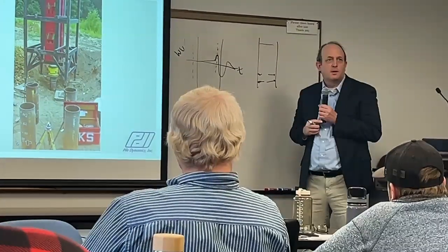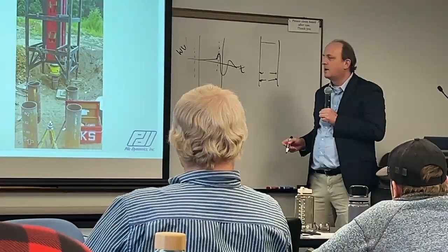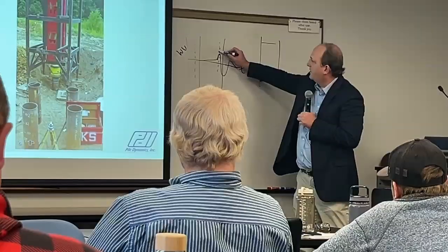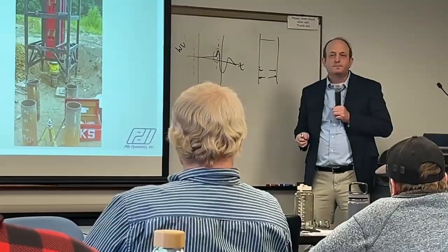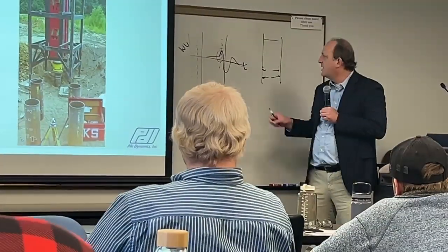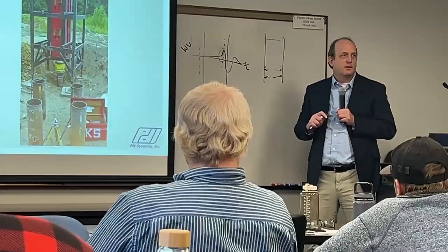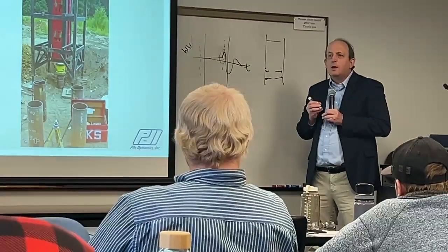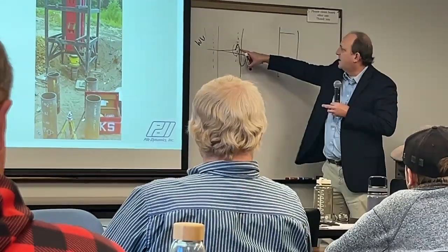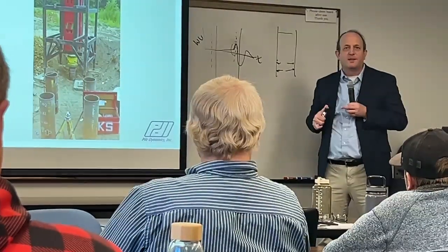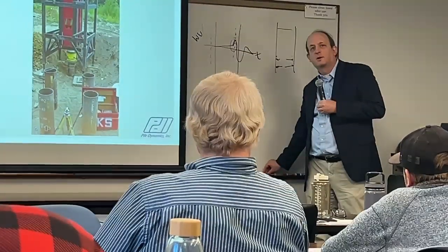When we're looking at open piles, especially 24-inch open piles, this is the behavior of the soil sitting inside the pile. So part of that will be modeled as resistance, and part of it gets modeled as additional mass, or as additional impedance, basically. As those piles get bigger and bigger, these types of things become less common unless the soil gets very dense or very stiff. And then it tends to go along for the ride a little bit better.